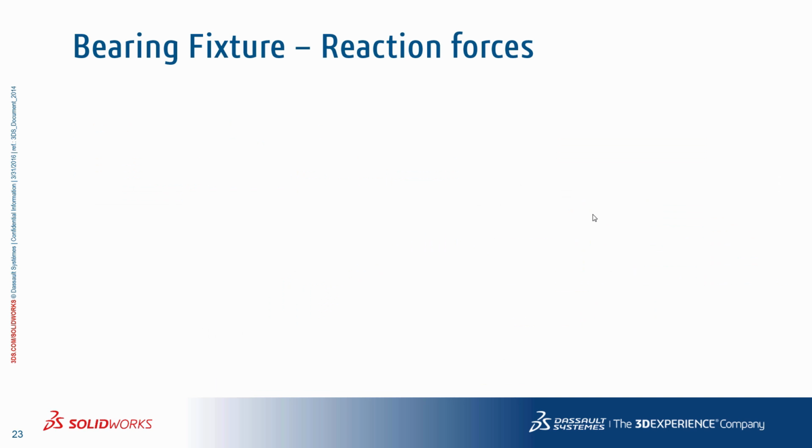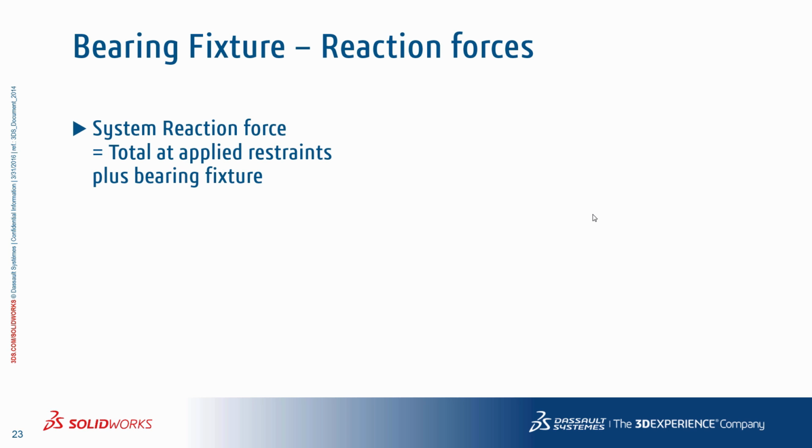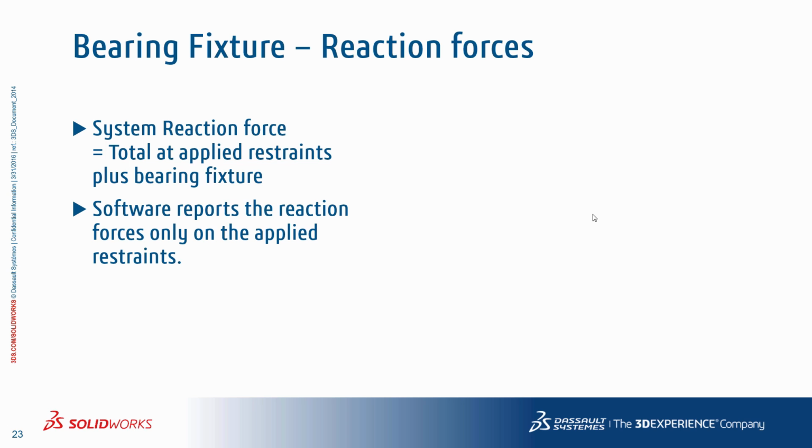Now, one thing with using a bearing fixture is getting the reaction forces. It's important to know that the total reaction force in the system includes the sum of the reaction forces of the applied fixtures plus the bearing fixture. In SOLIDWORKS Simulation, the reaction force is only reported at the applied restraints and not on the bearing fixture.